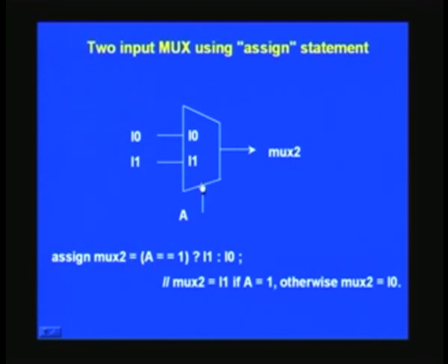Here you have a select signal, and this select signal must be first put here, and within brackets if you like. This is not the only way of writing. In fact, you can dispense with all this, including the brackets, and just have plain A, then also it will work. Or if you want, designers normally prefer putting 1'b0 or 1'b1 like that, because that gives an indication of how many bits of precision this signal has. Here of course it does not arise, but we can have even a multi-bit thing here as an assignment.